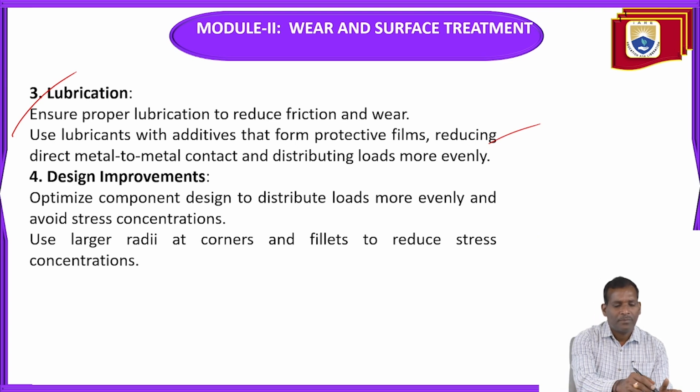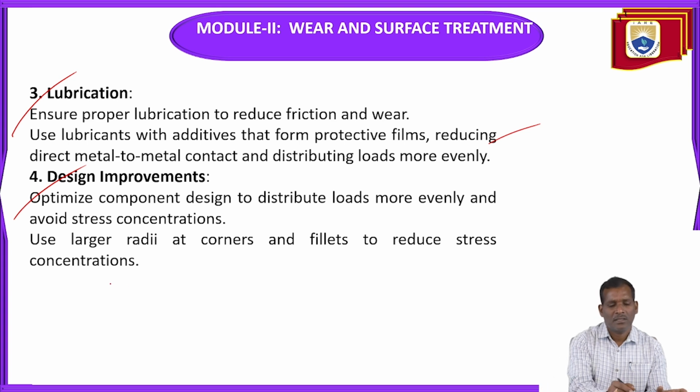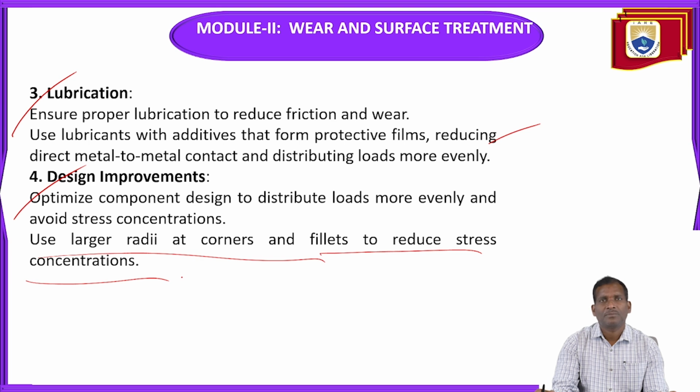So, design improvements. Optimize component design to distribute loads more evenly and avoid stress concentrations. Use larger radii at the corners and fillets to reduce stress concentrations. Whenever the component has irregularity or sharp edges, there is a stress concentration. To avoid this stress concentration, always prefer large radii corners.